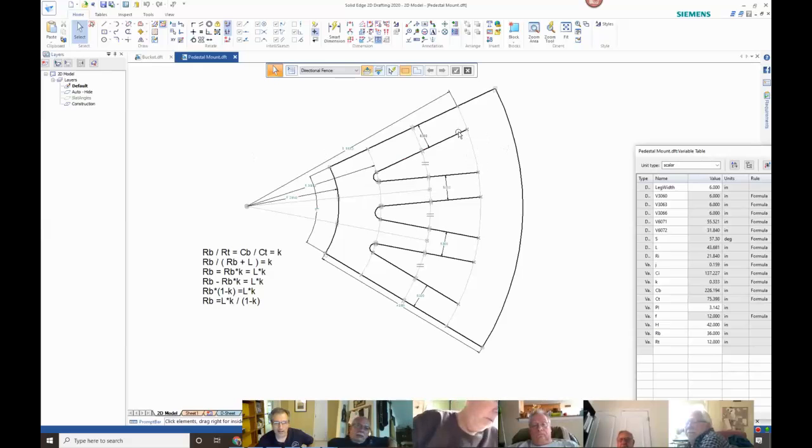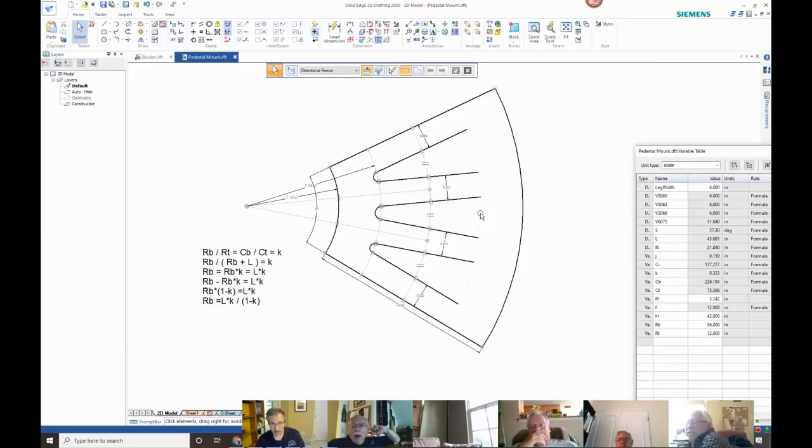I thought that the bottom of the cone was solid instead of the legs going all the way to the floor, so this is incorrect. I'm just going to get rid of this and show you a new command. Underneath, this is the split command. There's an option under there, extend to next.